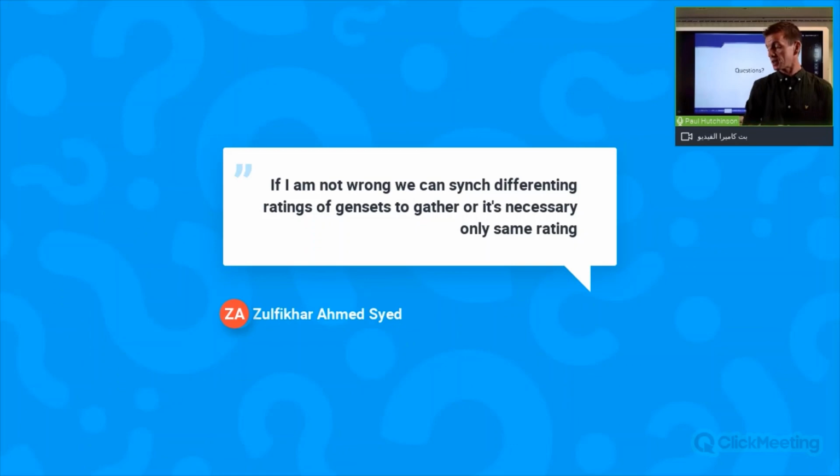Yes, you can synchronize different ratings of gensets. But they should all have the same synchronizer controller, and they will all load share proportionally according to their size. So yes, you can.